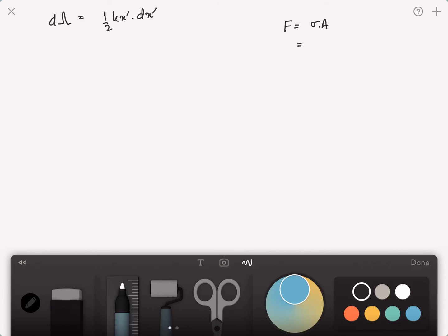And if I'm only looking at the axial stress in the x direction, because that was my whole hypothesis with the differential volume here, that this is x and F is acting in x, then the area will be given as dy dz.